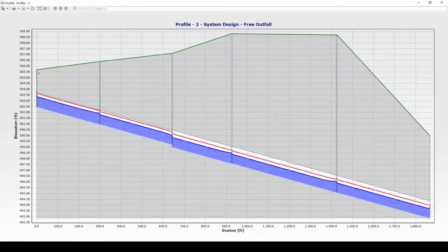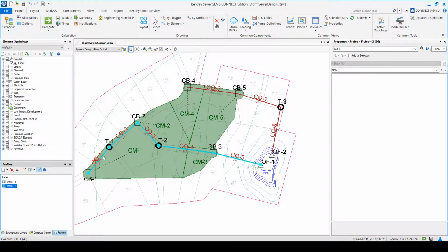It's exactly 2 feet of cover here. And then it had to maintain that slope. You see that the slope is pretty constant. It's the minimum slope we requested. That's why the cover at the end is a little bit bigger. So here we see 500 is the ground elevation, but the crown of that pipe is at about 494.5. So we have over 5 feet of cover there. And that's again because we set that minimum slope. So if I pay attention to the slope here, 0.005, 0.005.